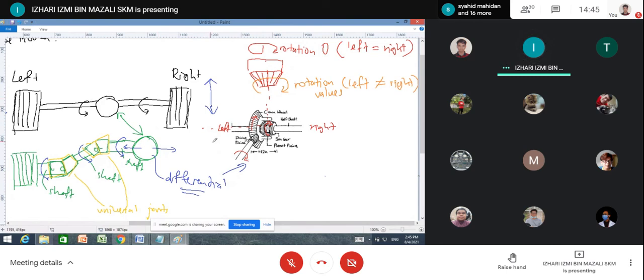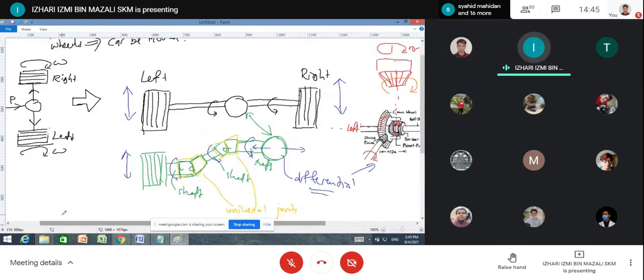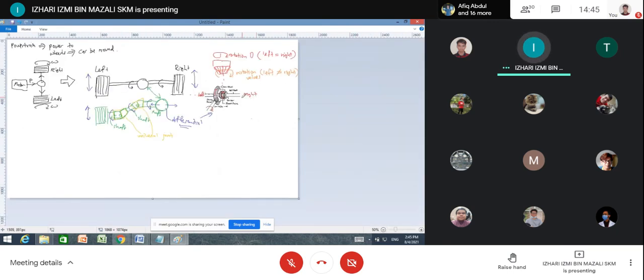So you need a differential, which looks somewhat like this. And then the differential here is connected to the motor. So you fix the motor. That means now your powertrain, at least in terms of the function, is working. Next, you try to design the joints and the supports to make your solution more detailed. This is one solution and one design in terms of the function. So the next step is to make it more detailed by including the joints and the supports.